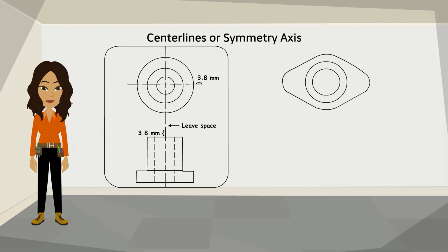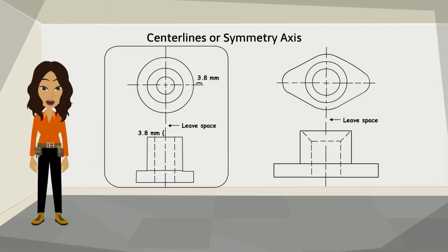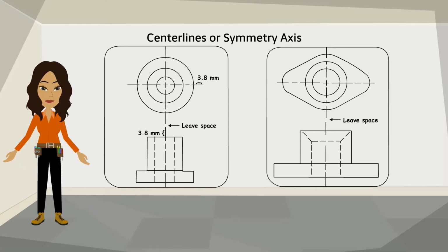Manual center lines. You can manually apply 4 types of center lines to individual features or parts in a drawing view. Center line to annotate the center of holes, circular edges, and cylindrical geometry. Center line bisector to create a center line that bisects 2 lines. Center patterns to create a center line on designs that have a consistent feature pattern. Note, if the pattern is circular, the center mark is placed automatically after you select all members.